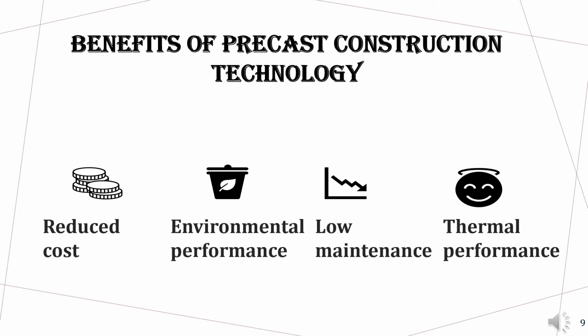This creative process absorbs project schedules, reduces safety risks, reduces site disturbances and lowers total project costs by having fewer construction companies and fewer workers on site. Environment resistant. Precast concrete structures have excellent resistance to fires, natural disasters, insects and molds. Like no other building material, its resilience to rain, wind damage, earthquakes, termites and decay has lower maintenance and insurance costs. It can also endure many freeze-thaw phases of winters better than other construction materials.